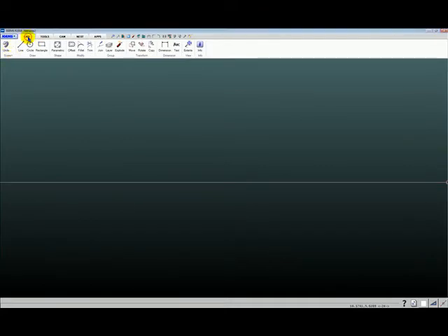When you first open up iGEMS, this is the screen that you're at. At the top, you've got these different tabs depending on which modules you've purchased. The CAD tab is generally where you'll start off. Across the top, on this ribbon, we've got most of your basic commands. On any of these menus, if you hover over the name of the menu, it'll show if there's a submenu, if it changes its shape or the highlight. There are less common commands underneath these submenus.